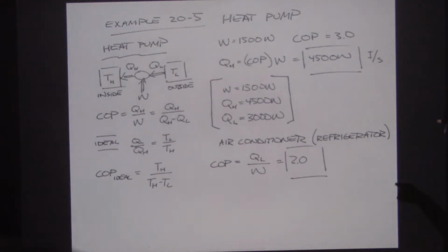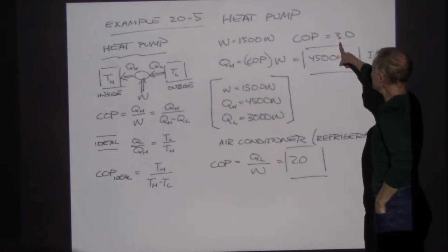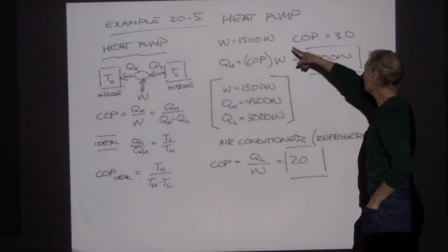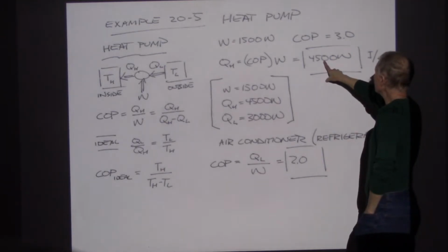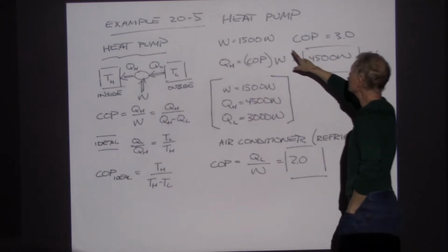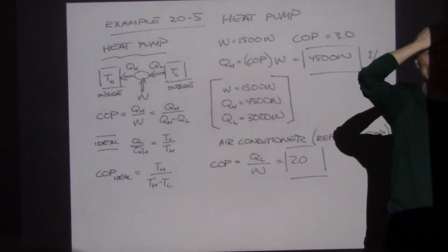As I mentioned, the heat pump that we put in has a COP of about 4, so you're only using 1/4 of the energy. In some sense, this thing is like 300% efficient, right? Because it's transferring 4,500 watts of heat, but it only required 1,500 watts of electricity to do that.